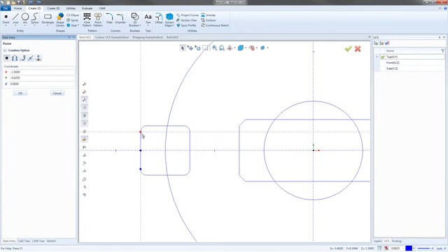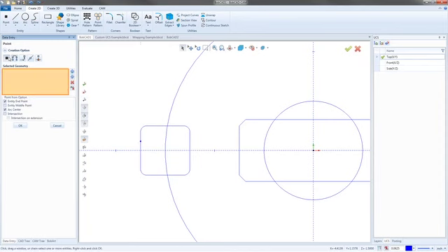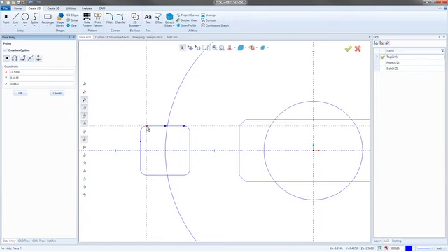You couldn't just randomly sketch a point on a line unless you went in and did some sort of change to it beforehand. You'd have to break the line, or use something like the points on entity to get it to a different position on the line. In this case, you still can't just randomly sketch on. You can't just go and click on lines now and it'll randomly sketch. It doesn't have to jump specifically to that one, but it'll also give you your snap points for just creating geometries, for just creating points.